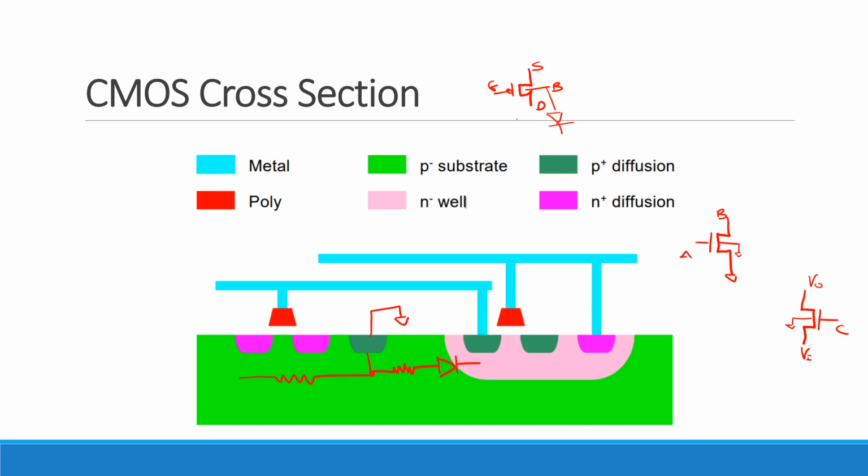In particular, you can imagine, let's say I have some digital circuit sitting right next to your analog circuit, right? That digital circuit has really spiky current waveforms. Those little spiky current waveforms usually translate into some sort of variations on the voltage. And if you have some really sensitive analog circuit, that could screw up things that you care about, okay? This is not a point we're going to spend a lot of time on for a while, but just keep in mind, it's usually the stuff that you didn't think about that can come up and bite you at some point, okay?